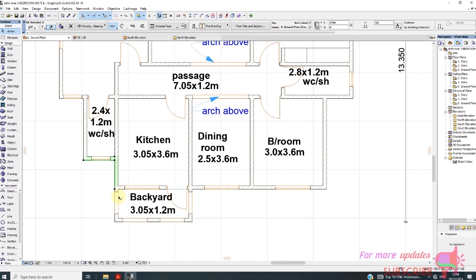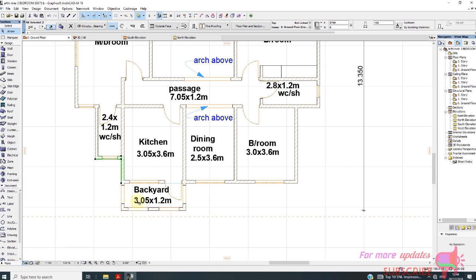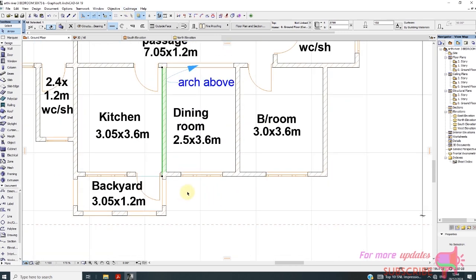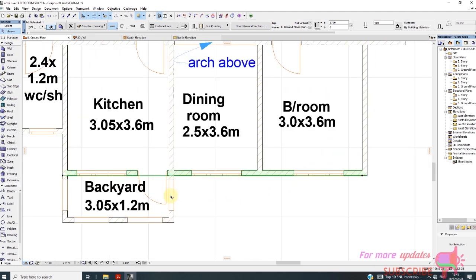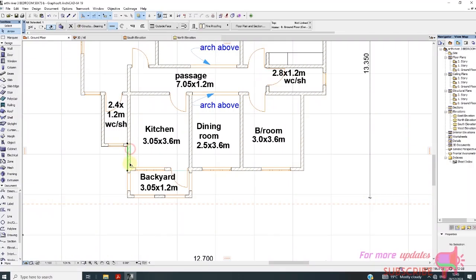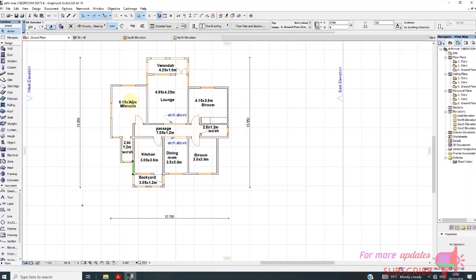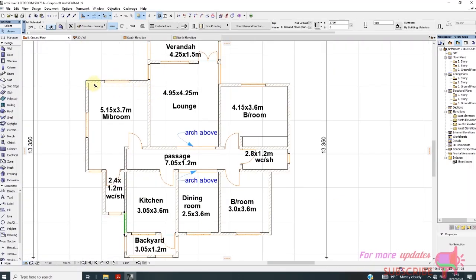If, for example, I want to use covering for a wall, or I want to intersect this wall, for example, because maybe I want to use wall covering in CAD image, before I intersect these external walls, I might need to split these walls at some point. So maybe let me select this one and this wall and then split it through that point. Okay, that is already split.